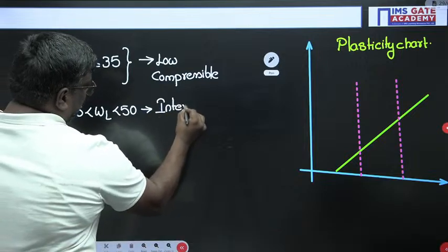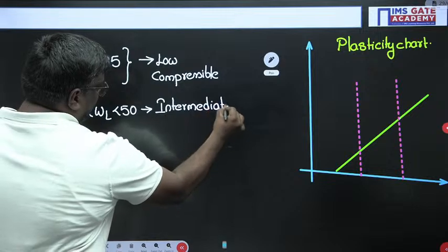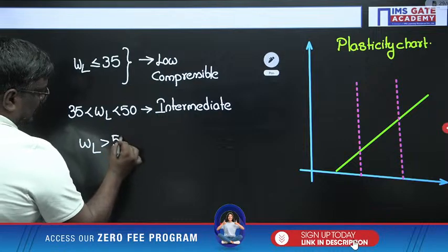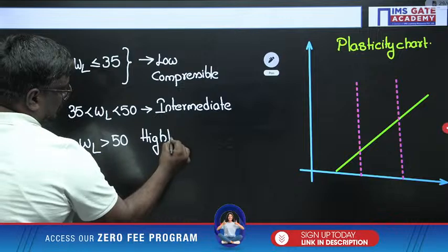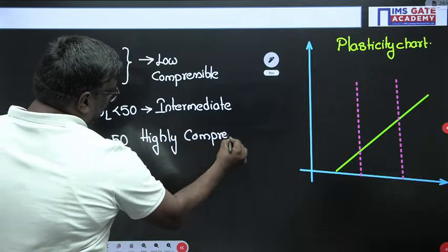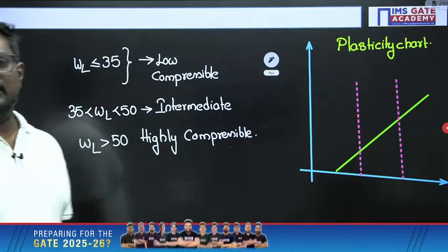And if liquid limit is more than 50, we call it highly compressible. And remember, my dear students, above A line, this is important.